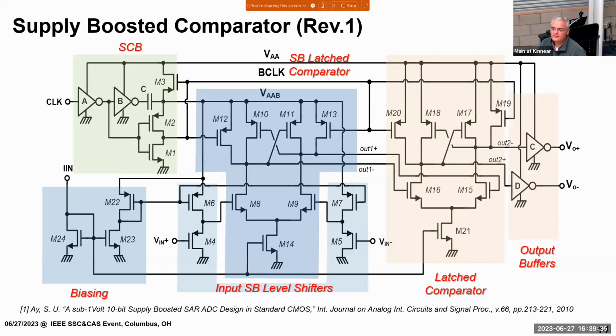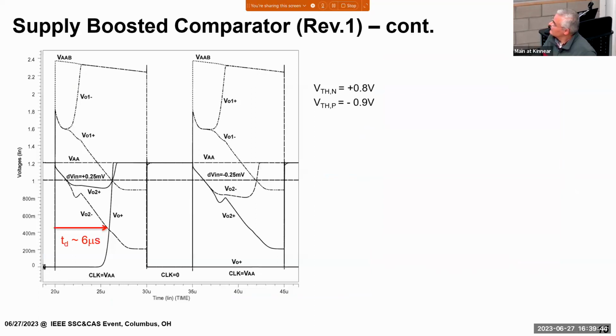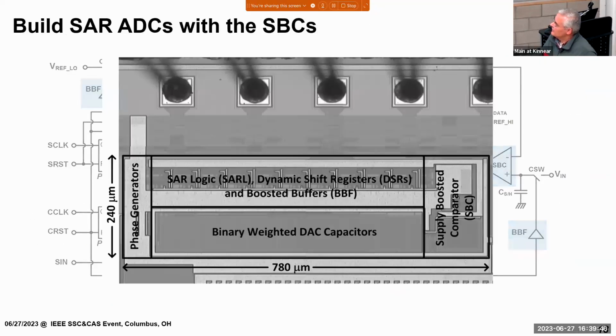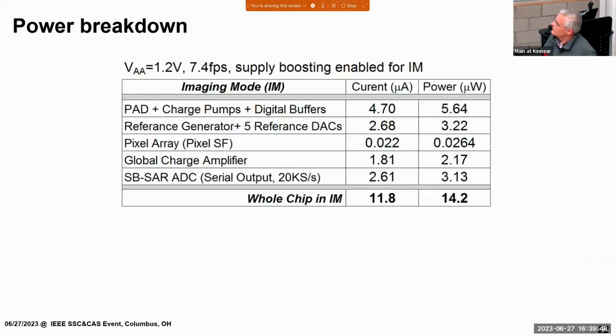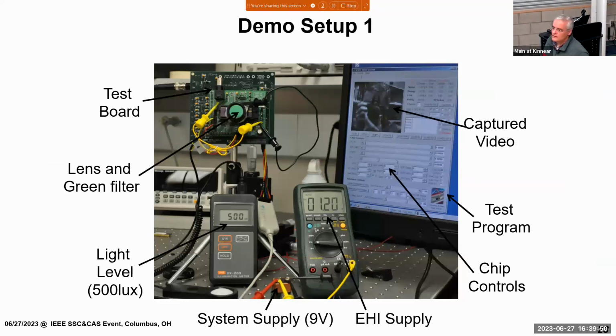So your tests are under 500 lux, right? Your image was taken under 500 lux. Yeah. Is it calibrated to that intensity? Because you know if you double it, you can almost double your FPS, and it's going to bring more harvesting but also increase the FPS. So you need to decrease the sampling time in order to have an image, right?